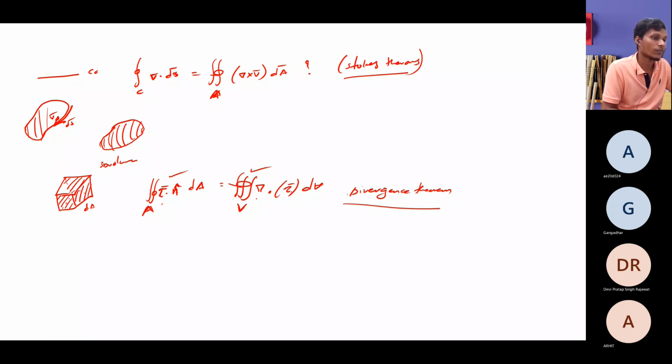And the last one is the mass conservation equation in integral form for a finite space. Let's write the mass conservation equation. Suppose d by dt of the integration over the control volume dV plus the integration over the control surface of rho u bar dot n cap dS is equal to 0. This is mass conservation.